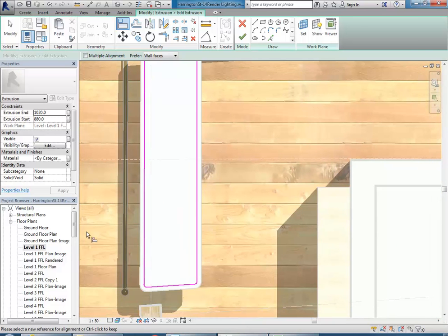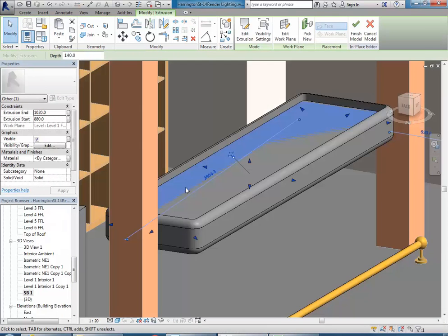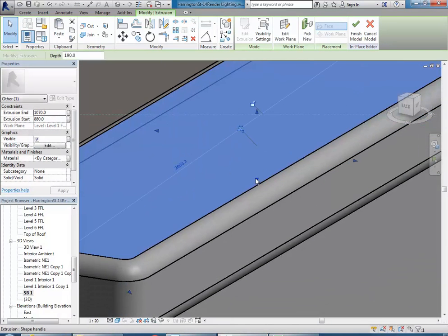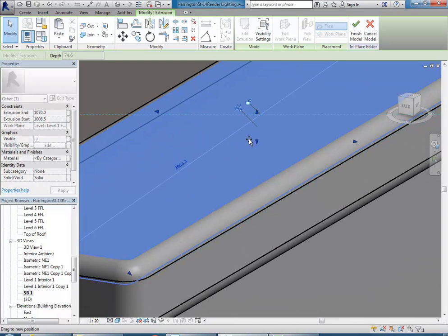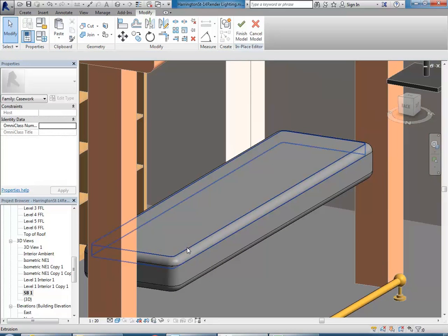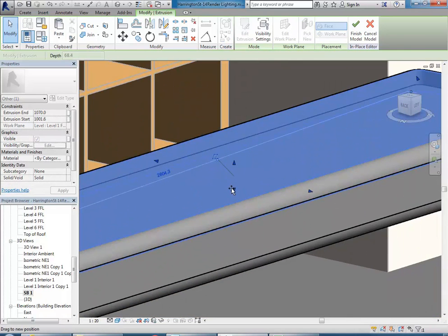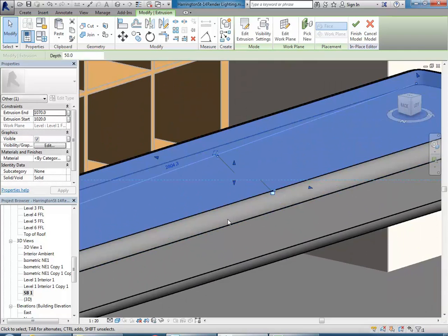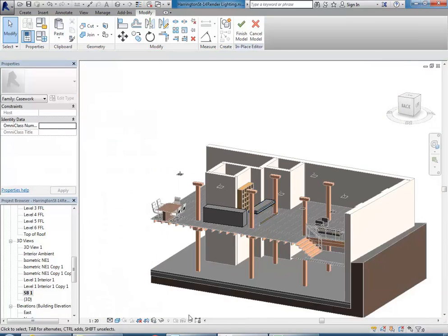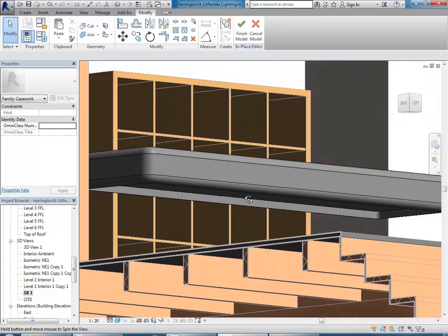There we are. So that's the insert, and once I finish it, back in the 3D view, you can just use the arrow there to stretch the top so that it lines up and it should snap, and then bring the bottom up again to snap to the base. Okay, so it's just that final piece, otherwise it'll have a hole. Maybe I'll do the section box through there so you can see it all in the end. I could leave the bottom out because that's where I'll put the lighting in.